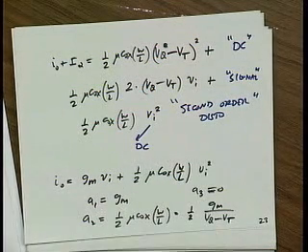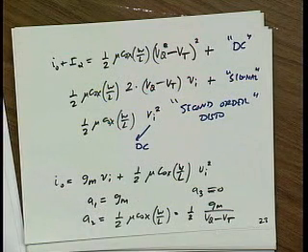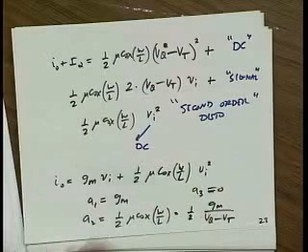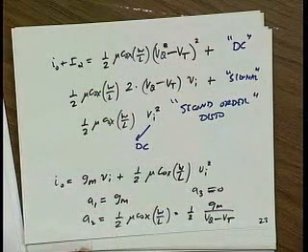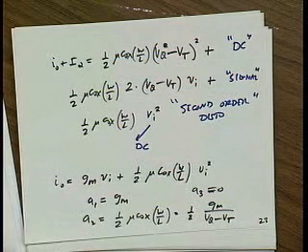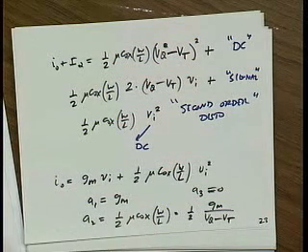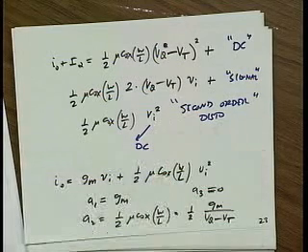In moderate inversion, it's actually a significant contributor to the current. We have to take into consideration the subthreshold device, where it's all diffusion current. So if you look at a more complete model, including the body effect, including all the parasitics, source-drain junction, let's say parasitics such as source resistance, you find that this model is not valid. In fact, source resistance is a very important one.